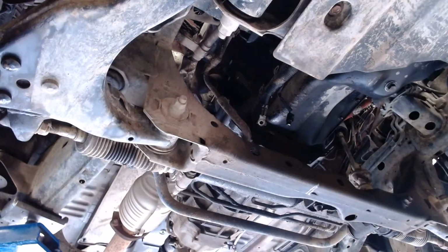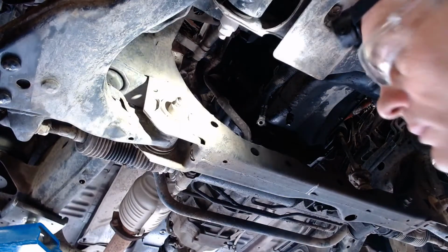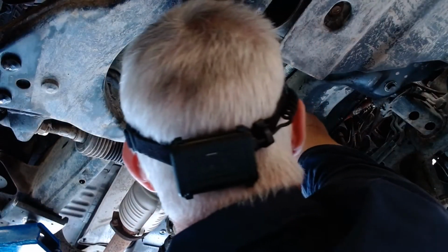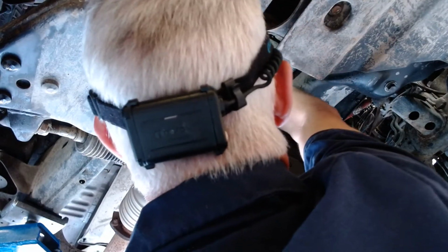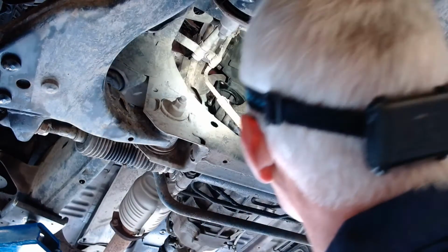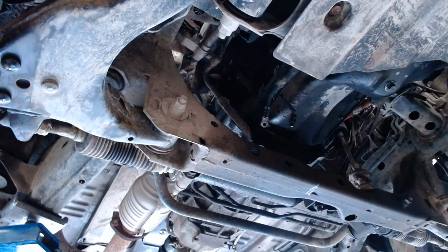And now what I'm going to do, let me see if the camera's in a good spot. I'm going to go ahead and take chem tool and a rag, put some chem tool on there and go up in there and just clean that surface of it. Just don't want the starter to not be sitting all the way down flush where it should be. Okay, good. Let me grab the starter.